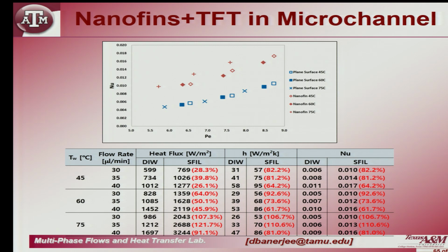So, let us say I have a big heat exchanger in an oil and gas plant or a chemical plant, the size of this room, for example. One way to make this heat exchanger more efficient is to put nano fins on the surface of the heat exchanger, right, which means I have to take it all apart, print nano fins, and push it back. The other way is you take the heat exchanger, flow nanoparticles for 2 hours, let the nano fins form, go back to flowing your pure water. You are going to get a better performance without the pump penalty of a nanofluid,